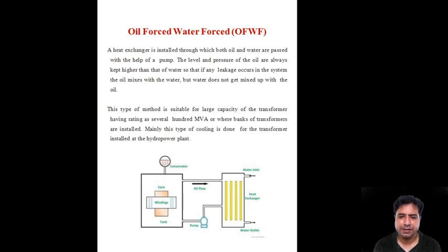The next one is oil forced, water forced. So here, just like oil forced, air forced, instead of using a blow of air, here we pump water in the heat exchanger. Water acquires all the heat of the heated oil, cools it off, and then that oil is pumped back towards the tank of the transformer.